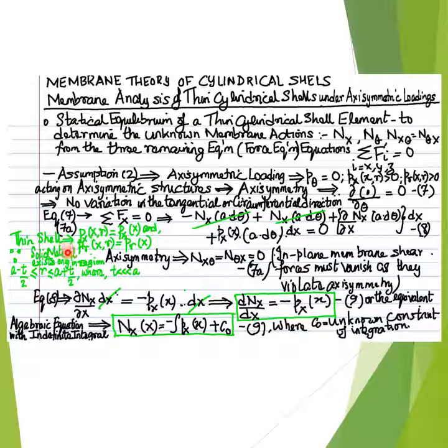Similarly, the external radial load PR, which in general for a general differential thin cylindrical element can be a function of the longitudinal axis x and the radial coordinate r of the selected choice of the cylindrical coordinate axis, will be a function of only the longitudinal or axial coordinate axis x in the selected choice of the cylindrical coordinate system of reference axis.